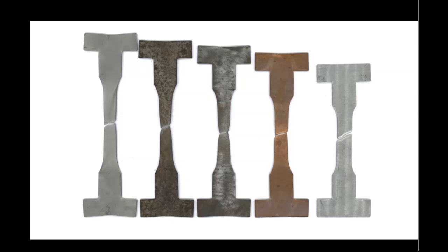So the material that is the most ductile elongates the most, and also the cross-sectional area or the neck shrinks the most. As the neck shrinks the most and its gauge length increases, the strain in that material will increase significantly. And this is another factor which the question asks.